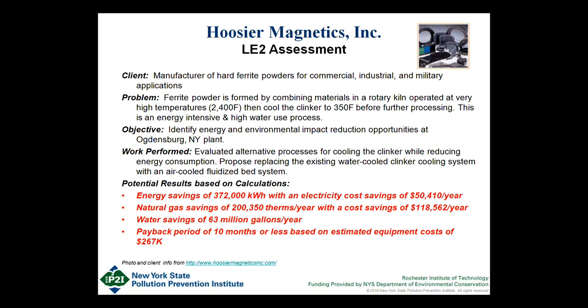In this case, they wanted to move away from their current technology, which was highly energy intensive. They had a cooling unit for their process that used a significant amount of water. So we wanted to replace what we call the clinker cooling system with an air-cooled fluidized bed system. We had to model their baseline, understand their current state, model their future state, and show them these potential results. You can see it's a significant amount of savings when it comes to energy and water, and the payback, which we always make sure we know up front when working with a company, was right in line with their ROI or payback period, so 10 months.